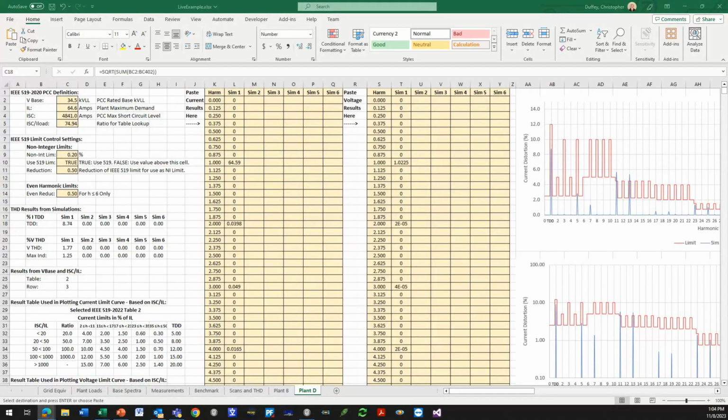Do many EV chargers cause harmonic distortion to the grid? It's all about penetration. How much, right? If you have one EV charging station on a very strong feeder, probably not much, unless the feeder was resonant right in the wrong place.